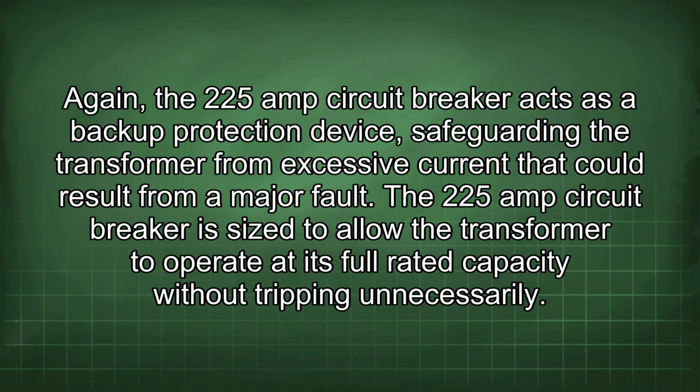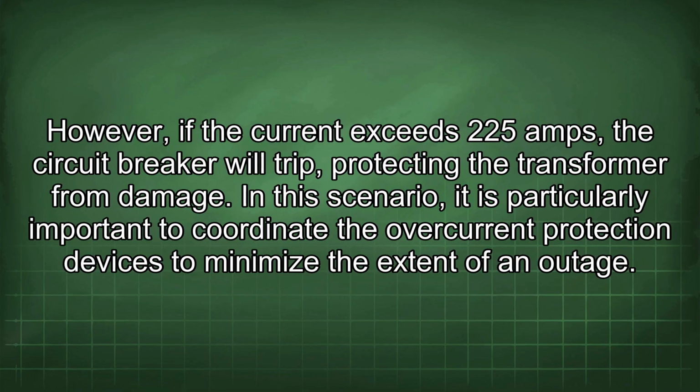Again, the 225 amp circuit breaker acts as a backup protection device, safeguarding the transformer from excessive current that could result from a major fault. A 225 amp circuit breaker is sized to allow the transformer to operate at its full rated capacity without tripping unnecessarily. However, if the current exceeds 225 amps, the circuit breaker will trip, protecting the transformer from damage.